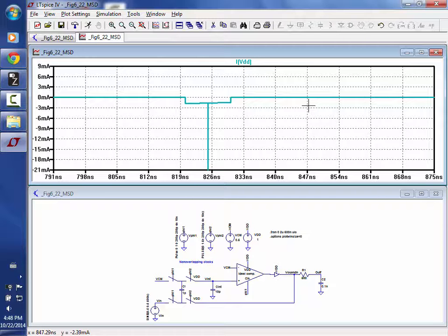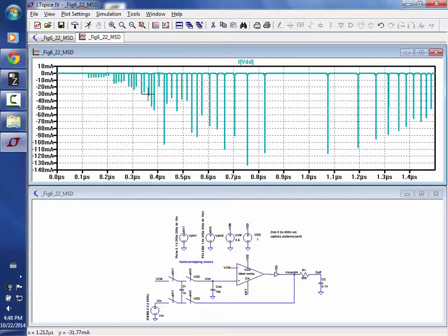So when I look at this and I say the RMS is 1.1, I don't believe it. I think there's some problem there, because you look at how much current's pulled, it's not pulled a lot on the average. And these pulses are tens of picoseconds in a microsecond scale, so I don't believe that measurement. All right, anyway, we got time, so let's cover one more topic.